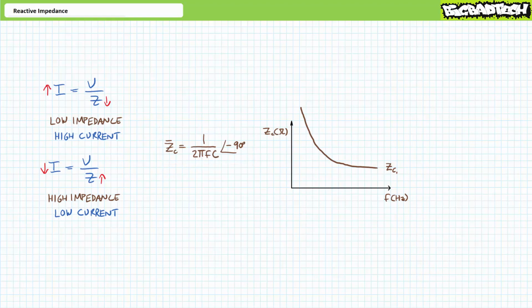The influence of these two properties can be most efficiently illustrated using a graph of capacitive complex impedance as a function of frequency. Given constant capacitance, small frequencies result in large capacitive impedance magnitude. Conversely, given constant capacitance, large frequencies result in small capacitive impedance magnitude. Frequency is the rate of polarity oscillation. Lower frequencies correspond to slowly changing waveforms, where 0 Hz, or no change, represents DC. Capacitors at low frequencies present large impedance.